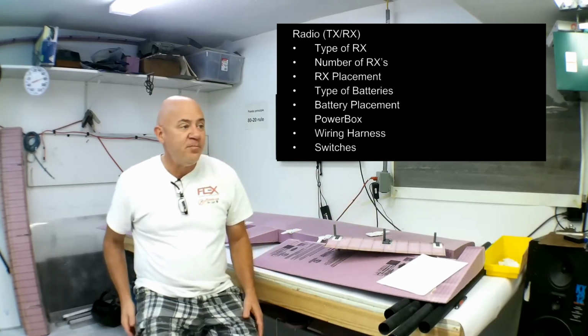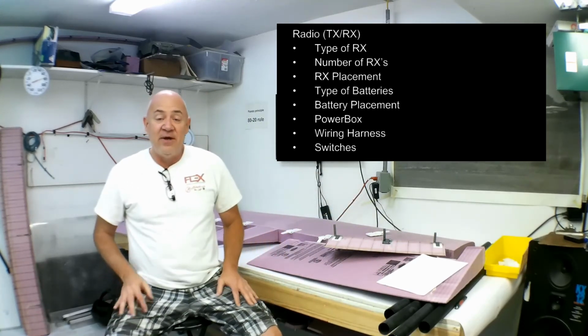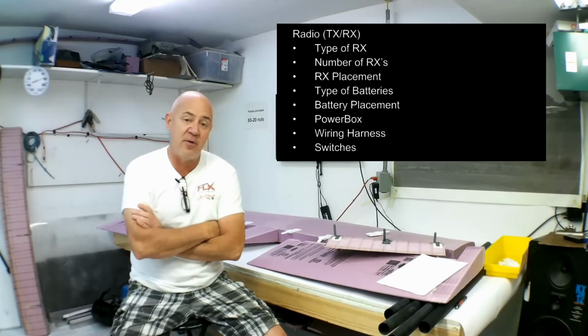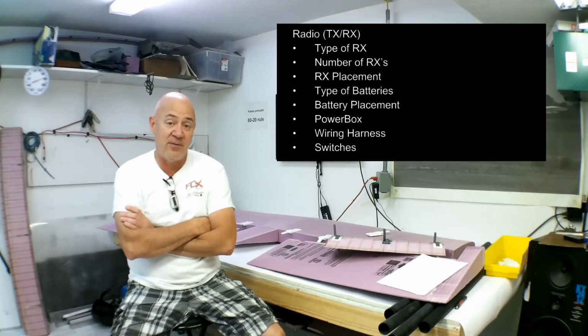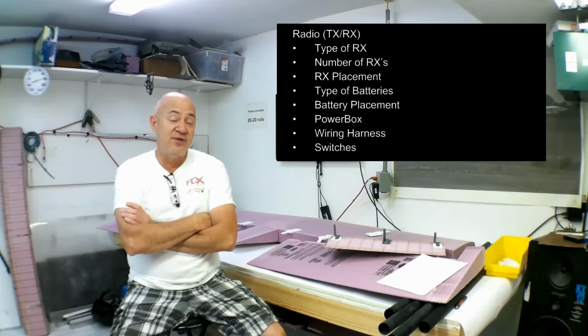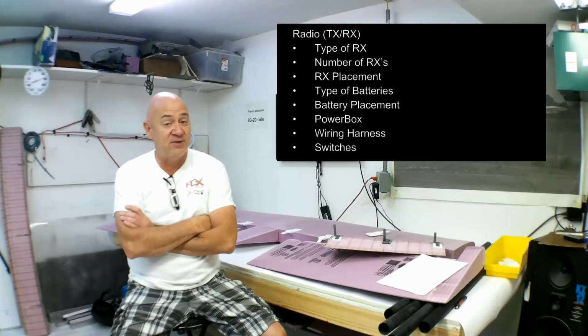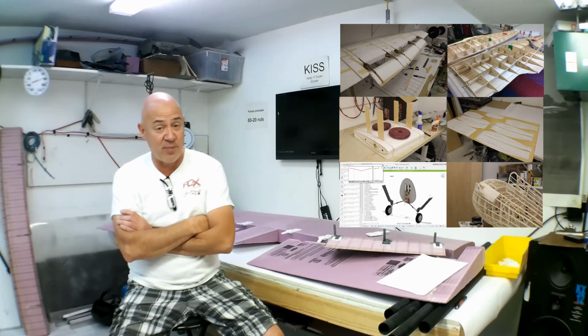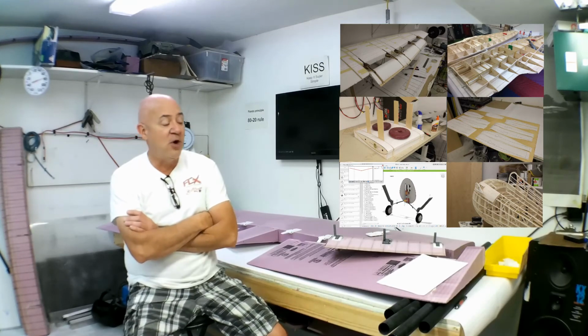Now, the last thing I want to talk about, if you're over 55 and under the 77 pounds, 2 ounces, you can inspect the airplane yourself. Since you built it, you know exactly what's in that airplane. If you're going to be at 77 pounds, 3 ounces, up to 125, an inspector is going to look at that airplane. So when you're building the airplane, you want a massive amount of documentation. You may want some service hatches, inspection hatches on the airplane that you can pop off and let the inspector look in there. So just keep in mind that you need to make the airplane so that you can get it AMA legal.